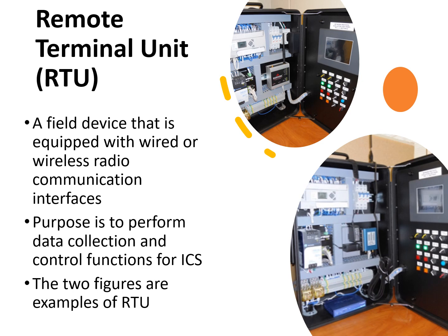A remote terminal unit, RTU, is a field device that is equipped with wired or wireless radio communication interfaces. Its main purpose is to perform data collection and control functions for DCS and/or SCADA systems. A PLC in the field that is remotely accessible and manipulated via radio signals is also considered an RTU.